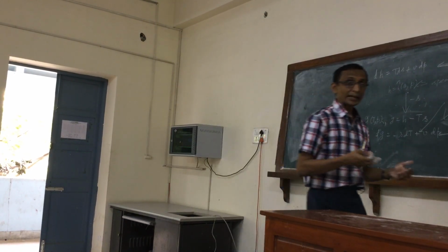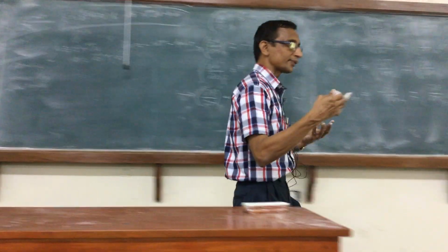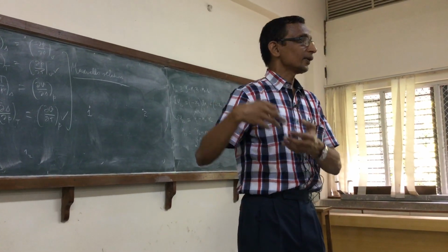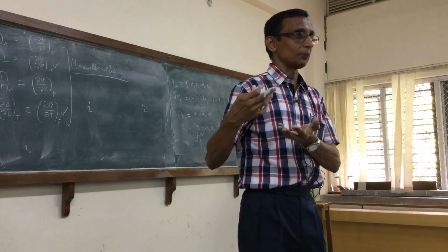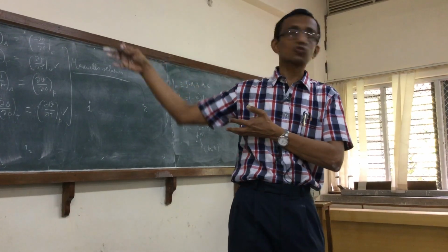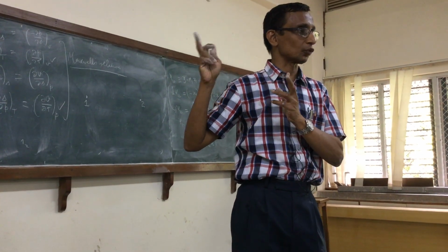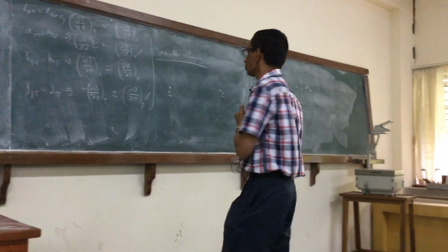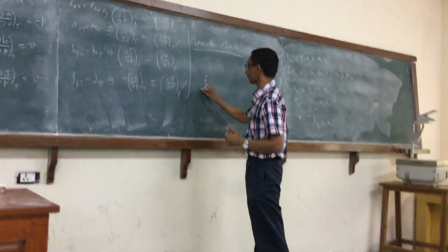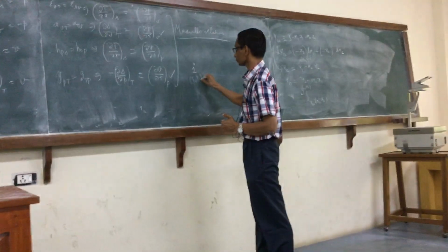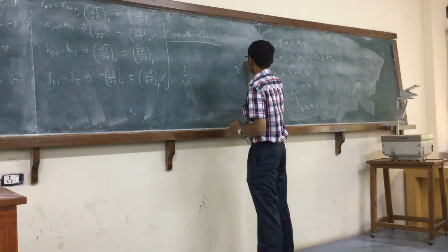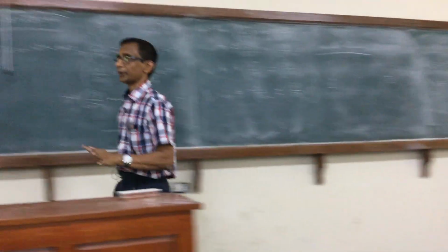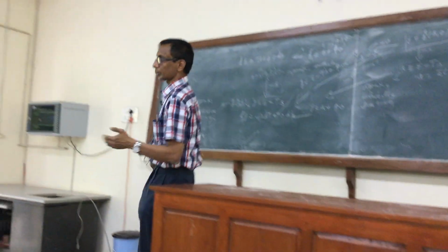But in actual practice, we are interested in changes in properties which take place between two states. Now, if these two states turn out to be equilibrium states, then we can use these equations to calculate the properties of those states and also the changes. So that is what we would like to do. Let us say a common specification of the states is through temperature and pressure. Most common specification. The gas expands from a certain temperature and a certain pressure.